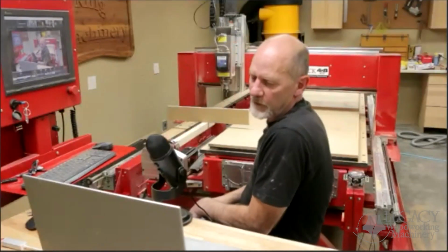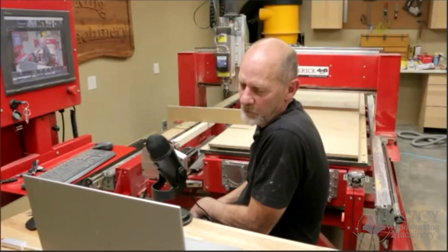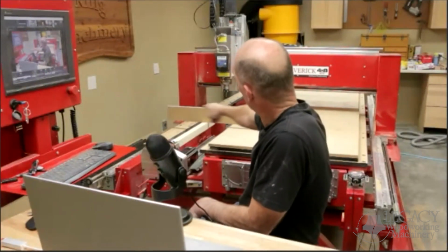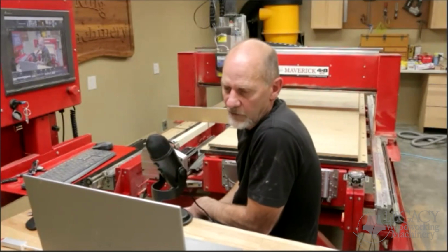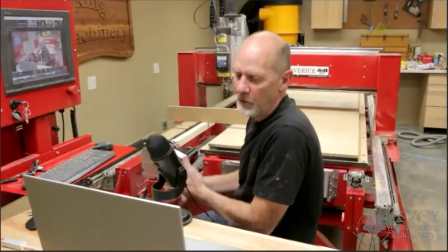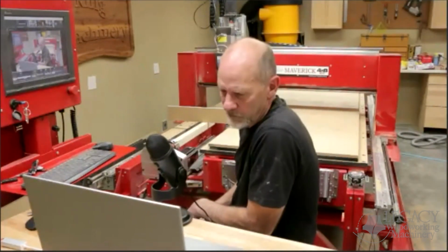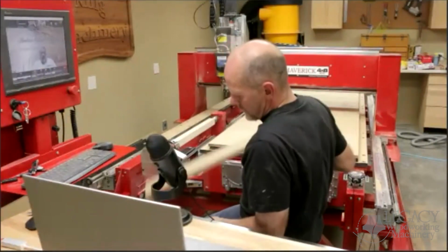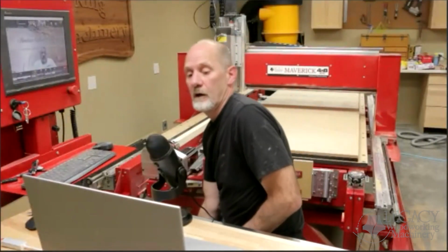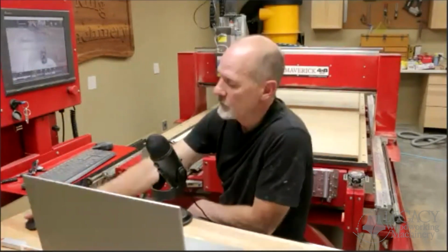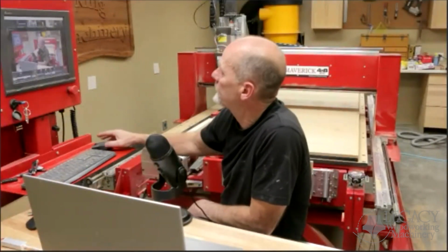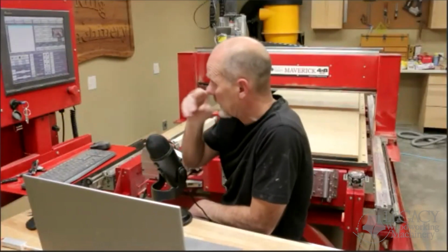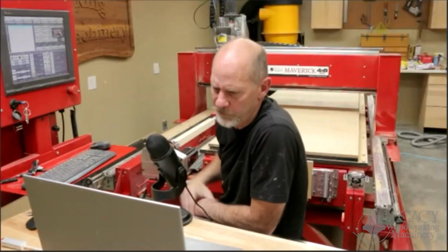Now, you can't see this, unfortunately. I don't have a camera on there, but the board actually rotated until it's level with the tailstock. And if it's not perfect, it's okay, because we're going to remove a little material, but that'll get you there really close. Do you want to zero your A-axis though, so it's zeroed? Yeah, that's a good question, because you can zero it right here on my screen. I can simply click on the A-axis and it will zero it.